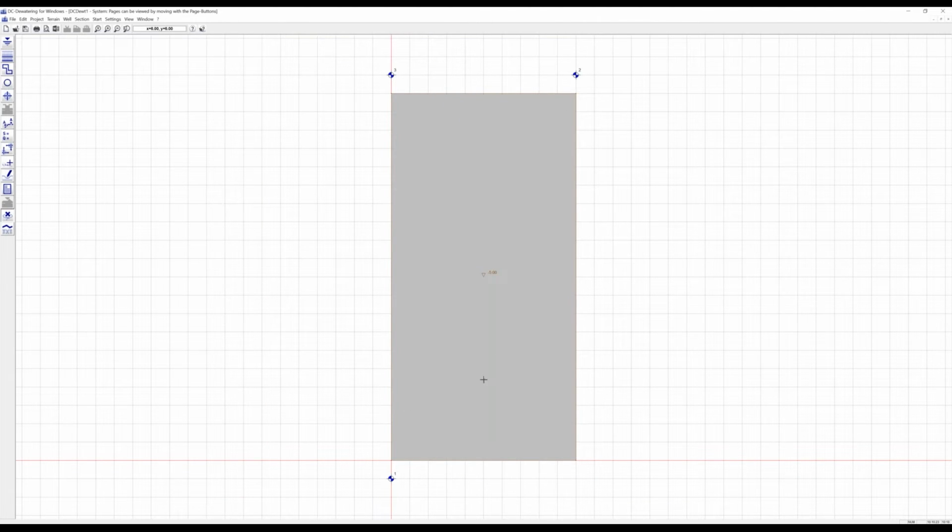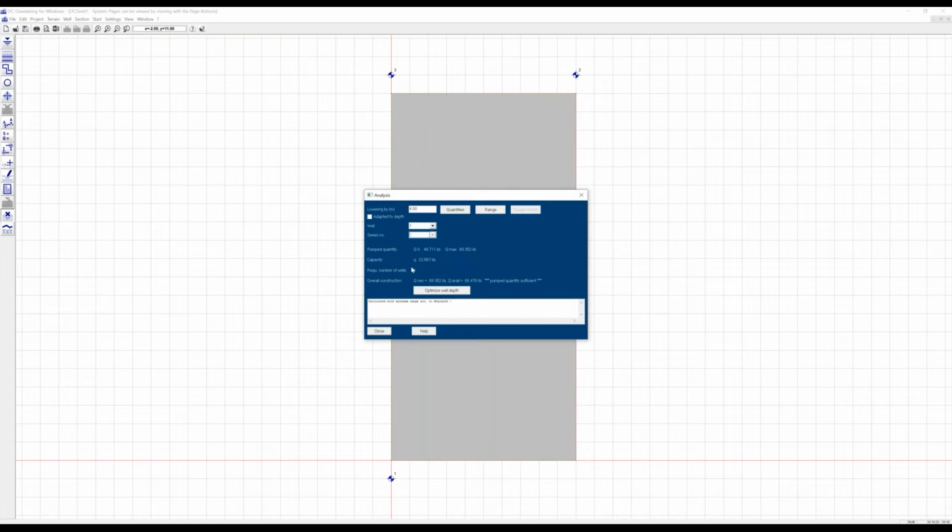And you see with 3 wells, our dewatering is fine. We have a total capacity of 68 liters per second, which is required. We have, for the first well, for example, the capacity of 22 liters per second. The second one is 23, third one 22, nearly 23. So in total, these 3 wells are sufficient to reach this dewatering that we need for this foundation pit.